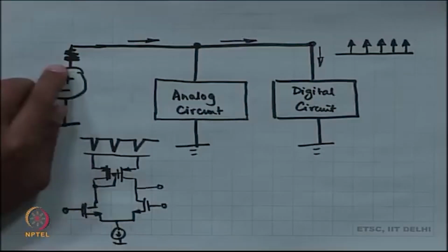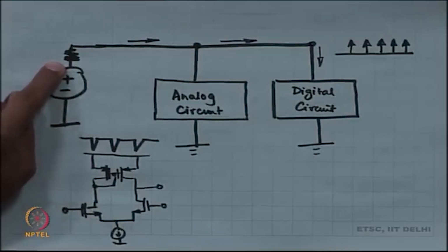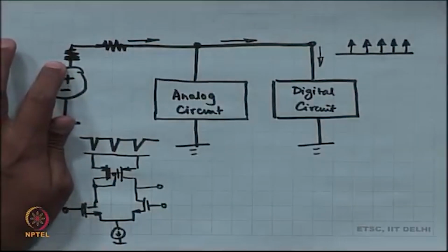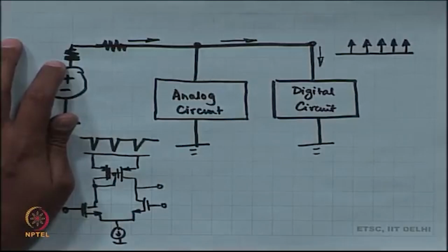All right. Here I said this is the source resistance of the battery. It is not just the source resistance. You could also have resistance in the wire, especially if the wire is long. What is going to be worse is if the wire has inductance, and invariably that is what happens. You know Murphy's laws.